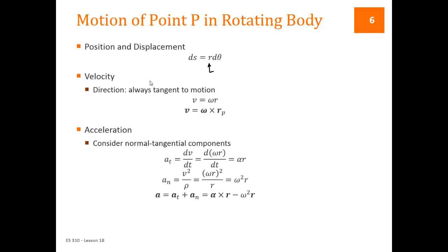So, to keep the directions correct, we have to remember this cross product, right? Because we're crossing r and omega in order to find v, and it's omega crossed with r. That is the order, and that order is important. We would only probably use these cross products if we were working in 3D. Most of our motion, we're just going to use omega times r because we're working in one plane. So omega is out of the plane, v and r are within the plane.